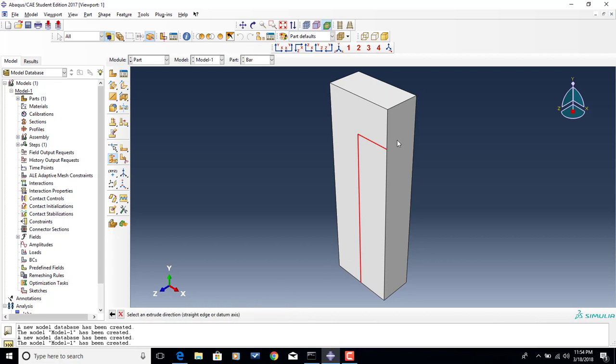So we're going to extrude, and I just want to click on the depth. You'll see the arrow shows up. Depending upon where your plane was that you had drawn, perhaps you need to extrude into the page or out of the page. It just depends on which way you went. In this particular case, Abaqus has assumed the correct direction. I can see it's pointing into the page. So when I say OK and create partition, Abaqus has now created this partition where I've got two different cells here.